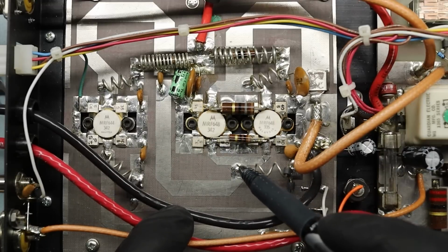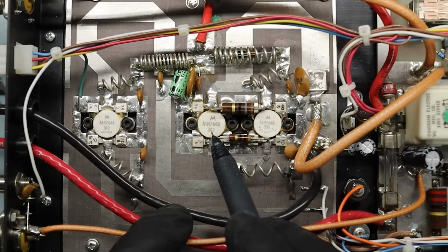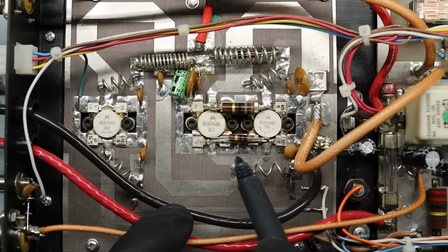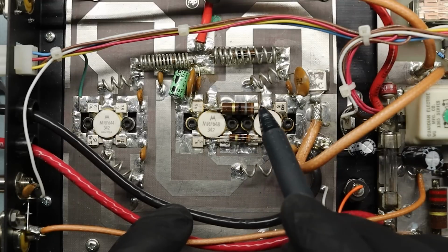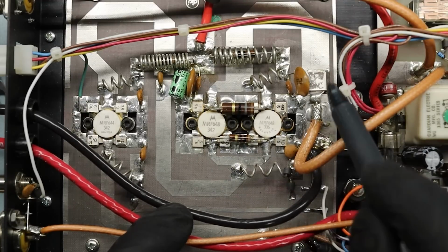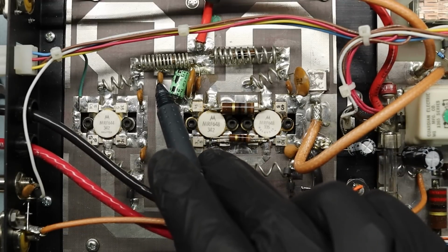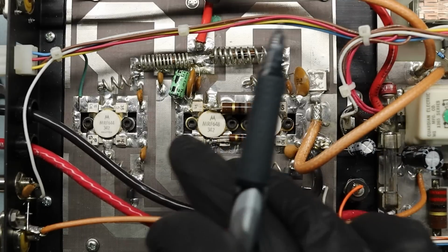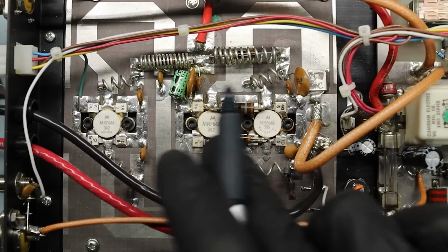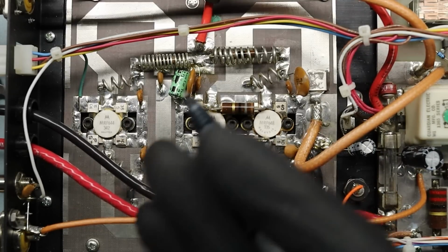This comes in through this, gets split off here. We have these two MRF 648s, okay? That signal goes off to the base, and this acts as kind of like a push-pull, and the output goes out to the coax. And so this capacitor is really what keeps each stage safe so that their DC bias points don't interfere with each other. I just thought it'd be cool to take a look at that.